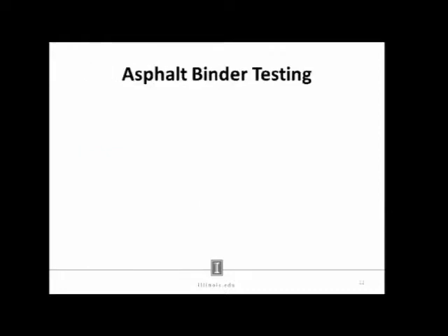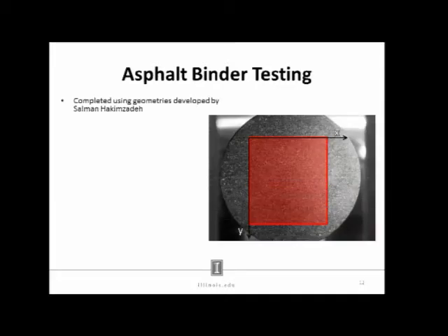that's up to you. In terms of the asphalt binder tests, again, it was work that I did with Salman. Salman developed the test. I just kind of thought it'd be interesting to take a look at asphalt binders in general. If you're going to look at digital image correlation with asphalt, it makes it a little bit easier dealing with an asphalt binder at a low temperature because that's probably about as homogeneous as you're going to get with an asphalt system. We ran IDT creep and fracture tests.